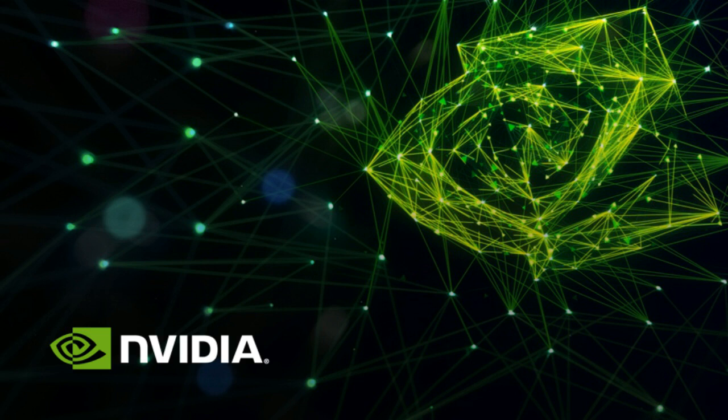This will be the last question, but please keep them coming on our developer forum, and we'll be happy to answer all of them. The last question is about Kaya. Does Kaya use G-mapping through RealSense? That's correct. We use G-mapping through RealSense, but we made it so modular that you could plug in, for example, a cheap LiDAR instead of RealSense on Kaya, or you could use Cartographer instead of G-mapping, or it doesn't need to be Kaya, a different robot. So all these parts are modular, so you can plug in. The G-mapping algorithm doesn't actually know we are using a RealSense camera. We just have a driver for RealSense. We get data out of it, we convert it, and feed it to the G-mapping algorithm, for example. So it's super flexible. You can change any parts of this flow.